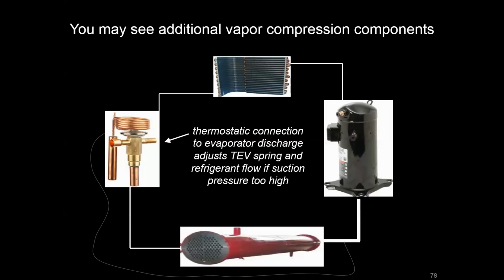And what the expansion valve can do is actually have that temperature change be registered and change the pressure on the valve, and it'll move something like a needle inside the expansion valve so that it can change the flow of refrigerant going to the evaporator. So it's essentially a way to automatically regulate the flow as loads change to the evaporator.